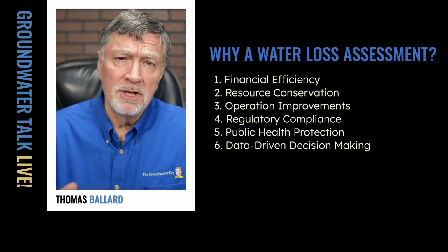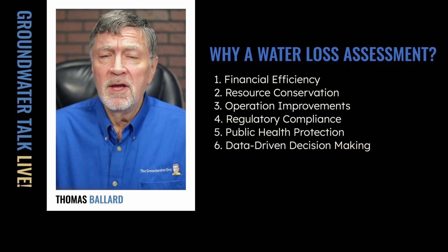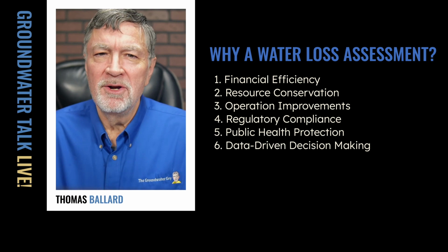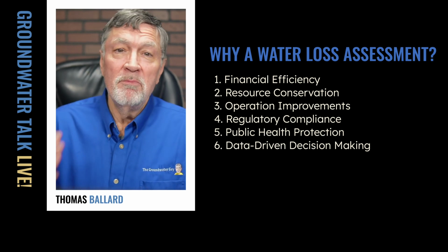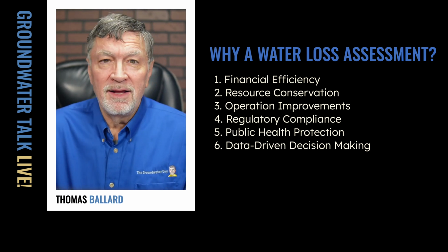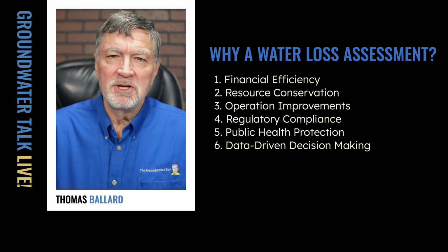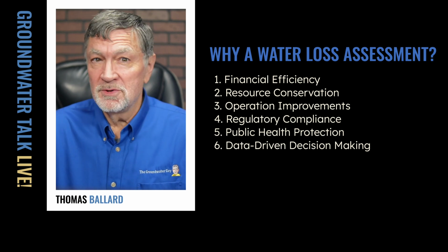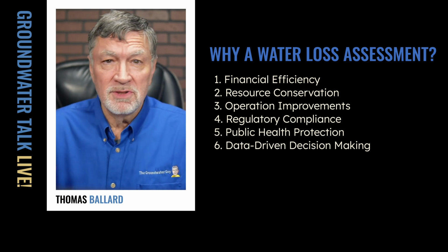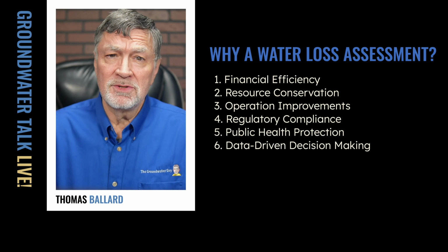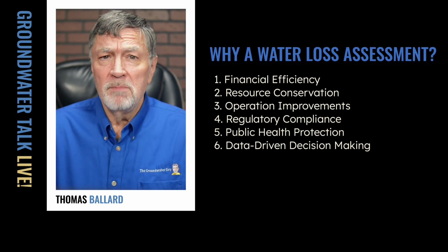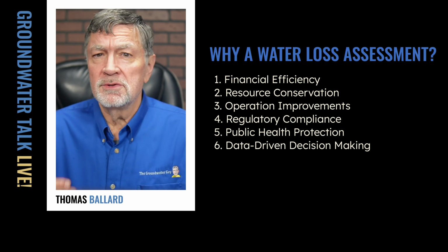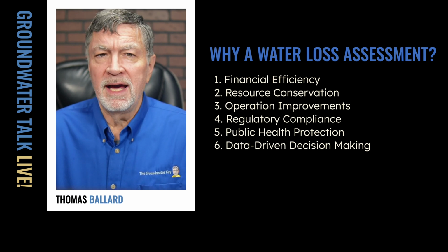And we're going to talk about meters too a little bit. Really, we're moving away from more of the unmetered consumption type of thing, but it's still out there. It makes it a little bit harder to differentiate between unmetered consumption that's authorized versus unauthorized leaks and thefts and things like that. So if you can do meters, that's definitely the way to go, because it's going to give more accurate data.